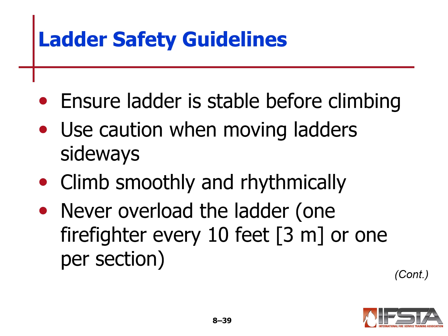We also want to ensure the ladder is stable before climbing. When you reach out, you set your 75-degree angle or near it, you stand on that bottom rung and make sure that it is seated. If it's in grass or gravel, it's seated, locked in the ground. If it is on pavement, chances are you're going to have somebody constantly heel it. And we should be heeling ladders when people are climbing as much as possible.